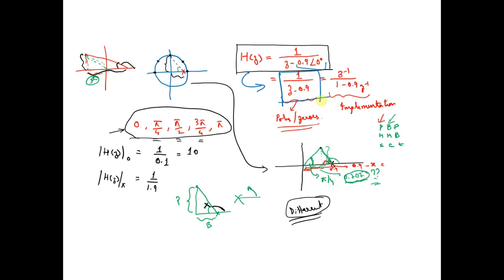Now this equation will be used for determining the poles and the zeros. When you try to find out the location of the poles and the zeros, you have to see that the power of z is positive. So in the numerator there is nothing, it comes out to be 0. In the denominator we get z equals 0.9, where it is here. You're getting my point.